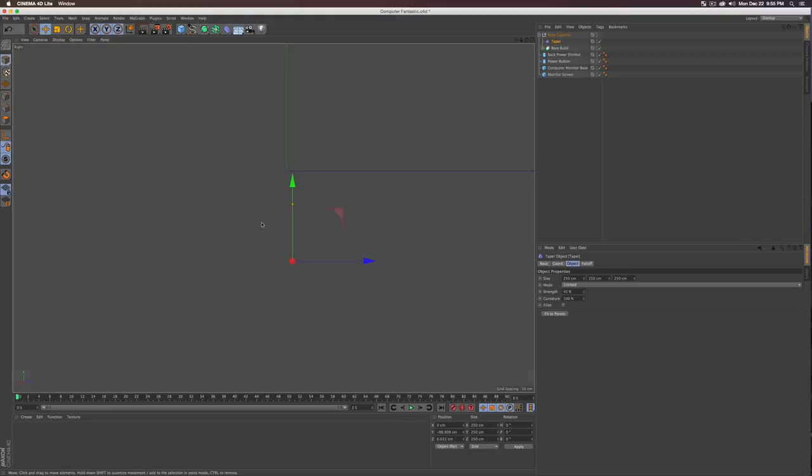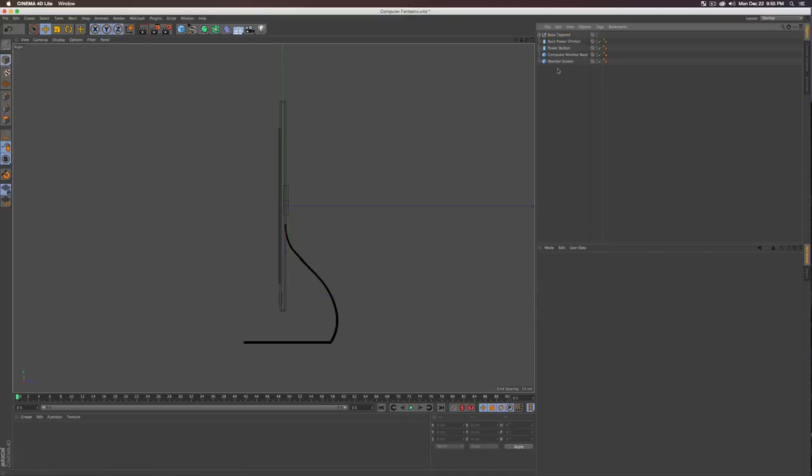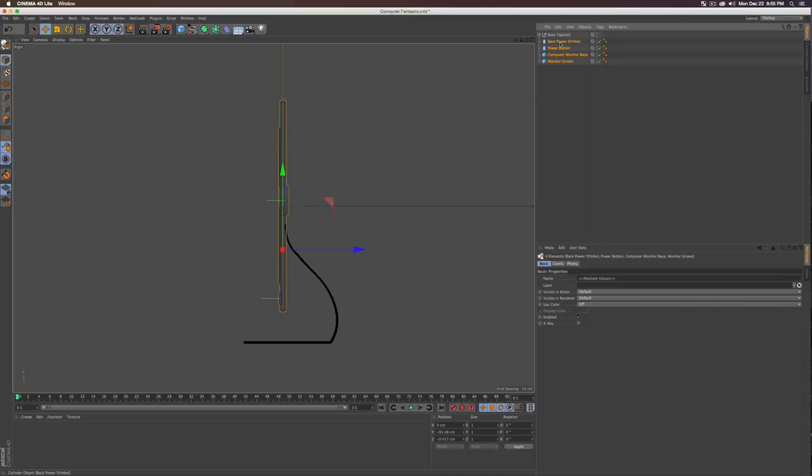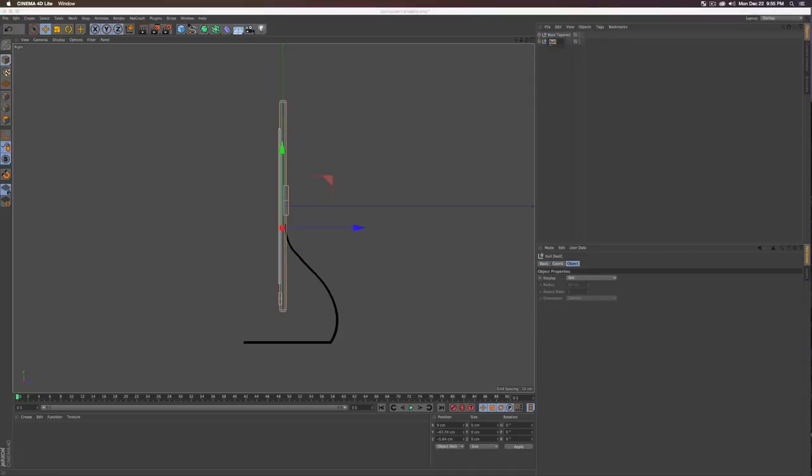Let's jump into our side view, F3 on the keyboard, or this little guy up here. And first we're going to hide our deformer. So double click this little traffic signal at the top one, so it turns red. And then on all these other options right down here, let's group those two. So grab them, press Alt-G for a null, and I'm going to call this computer top, I guess. I can't really think right now.